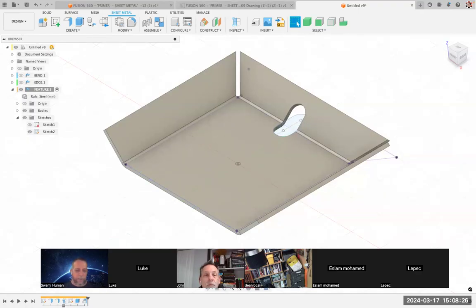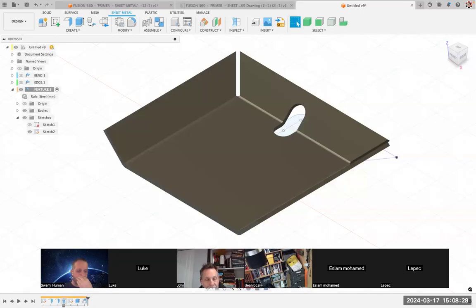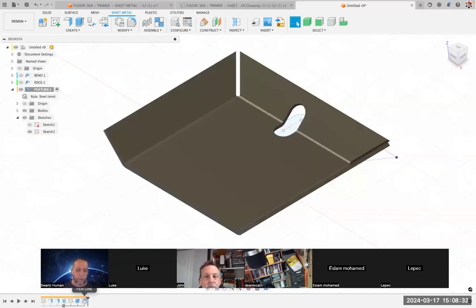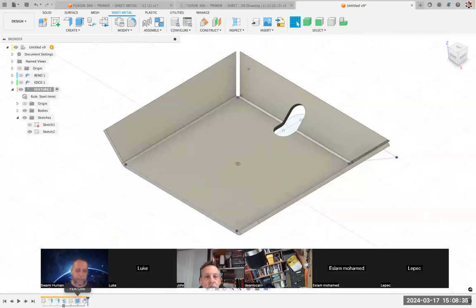So now in the timeline, it created a group with bookends. One is unfold. The other end is refold. And it has all the stuff inside it that we did. And we can hit the little plus minus here to expand or collapse, open or close that group. If I have that group closed, when I go back one step with my VCR controls, then we will be at the point where we don't have it. And if I go one step, it goes through multiple features in that group. And there we are.